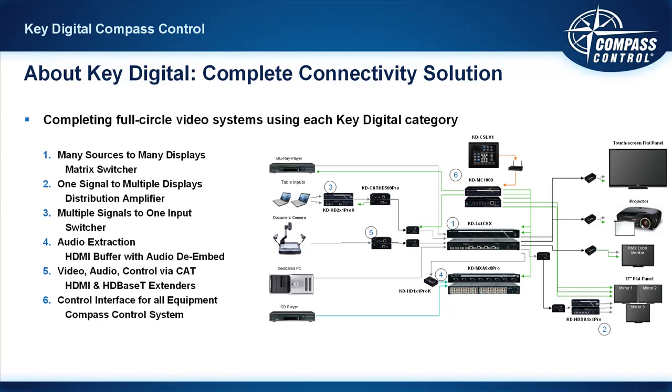Now, when it comes to your first Compass Control project, you should be referring to a system design schematic similar to this, perhaps with many audio, video components. How are those things wired into and out of your matrix switchers? Because the programmer needs to program that to know that this is output 1, output 2, output 3, output 4, because those are all different commands, aren't they?